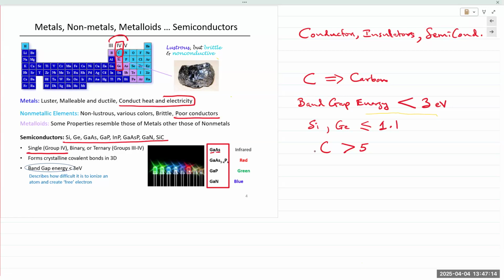So the question is, does the band gap energy make the LEDs different colors? The answer is kind of yes, because the material property is different. So yes, it is a different band gap, but that's because the material itself is different. We are using different materials, and there's something known as doping or impurities that we'll look at in just a few slides, that gives us different colors.